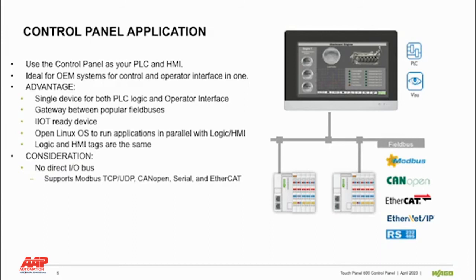It supports most of the popular fieldbuses, so it can be used as a gateway to many different types of devices. It supports Modbus TCP, CANopen, EtherCAT, EtherNet/IP, and serial interfaces like RS-232 and RS-485. It is IIoT enabled for direct connection to a cloud or enterprise-wide SCADA system. It can also run Docker containers in parallel with your eCockpit applications, and all the tags for your PLC and HMI are in one unit.